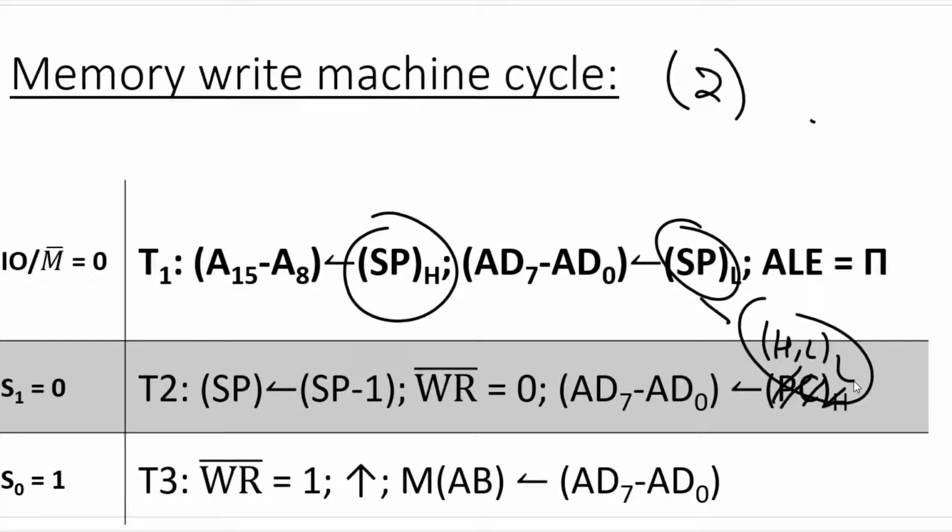Now whatever was in the HL register pair has been written onto the stack pointer, but whatever was on the stack pointer has been written to WZ. We need to transfer from WZ to the HL register pair. Along with this, the HL register pair will now carry the data that will be transferred from the WZ register pair. So this completes the instruction.